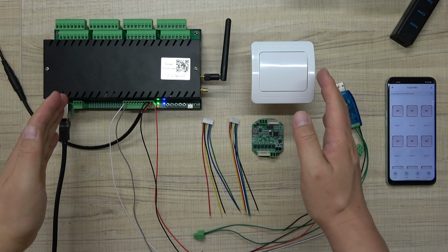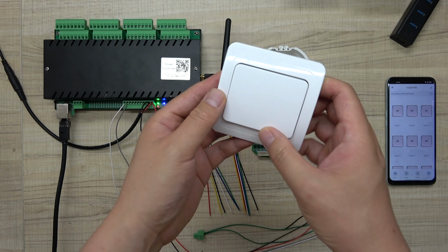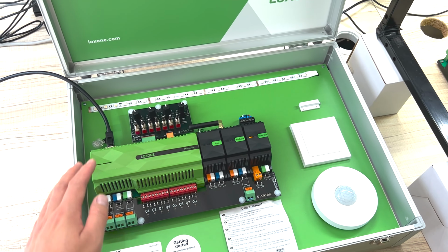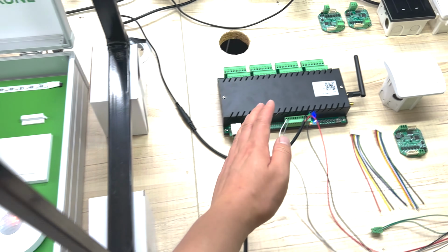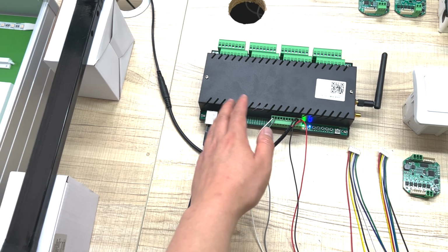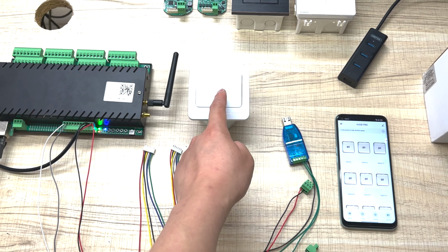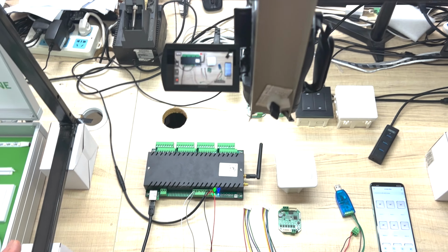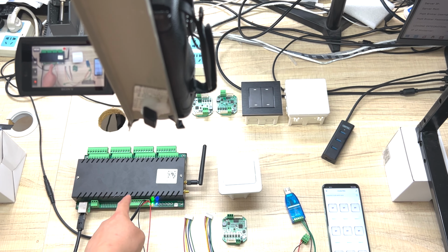Hello everyone, in this video I will show you how to integrate this traditional older switch to the Loxone system by KinCony relay controller. See here, that is the Loxone demo case, that is the mini server, and this is the KinCony relay controller. I have integrated this relay controller H32B Pro to the Loxone mini server. In this video I will show you how to use this traditional switch and work with the Loxone system. I take this video for you step by step, showing how to do it by this RS485 interface.